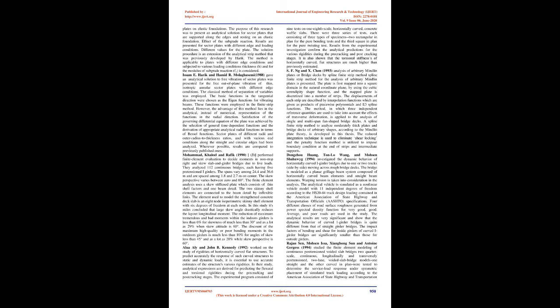Cheung and Chen, 1993, Analysis of arbitrary Mindlin plates or bridge decks by Spline Finite Strip Method. Spline Finite Strip Method for the analysis of arbitrary Mindlin plates is presented. The plate is first mapped into a square domain in the natural coordinate plane, by using the cubic serendipity shape function, and the mapped plate is discretized into a number of strips.